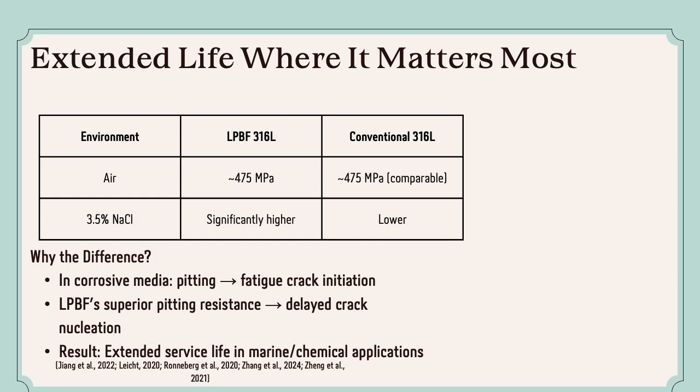The reason is that corrosion pits often act as initial sites for fatigue cracks. Because LPBF 316L generally has better pitting corrosion resistance, crack initiation is delayed and fatigue life is extended. As a result, LPBF 316L is particularly attractive for marine, chemical, and other corrosion-sensitive applications.